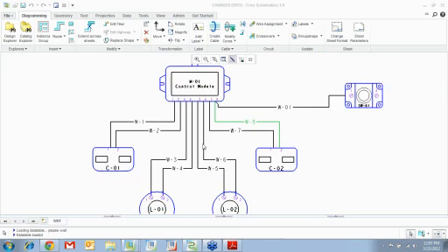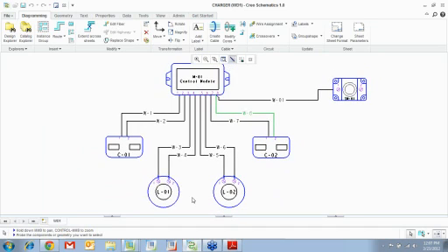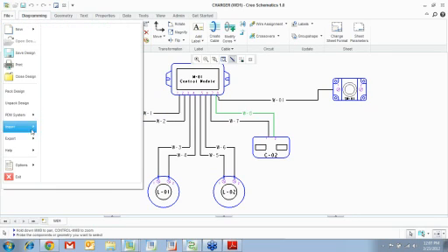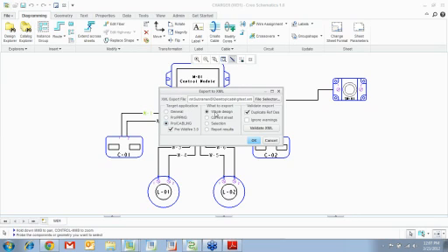Alright, so that's how we pretty much create this whole wiring diagram. We added all these symbols, we changed the model name parameter, we went to the ports, we added this entry port parameter for the ports, we routed the wires, and we applied the data set to the wires. Now once you do this part, you go File, Export, and you want to export it as an XML file. So you export it as an XML file and you hit OK.